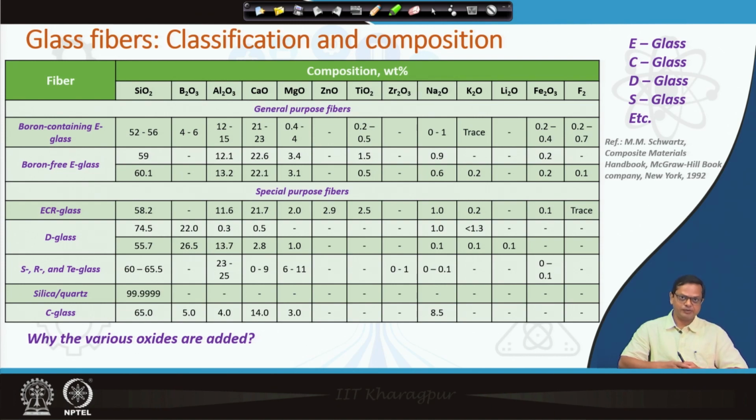What is the advantage? If you remember how glass fibers are made, I talked about 4 basic techniques: wet spinning, dry spinning, melt spinning, dry jet wet spinning. Out of that, which one is used to make glass fiber? Yes, you are right. To make glass fiber, we use the melt spinning method. That means if the melting temperature of the material is lower, it is easier. The melting point of SiO2 is generally around 1700 degrees Celsius, to be precise 1710 degrees Celsius.